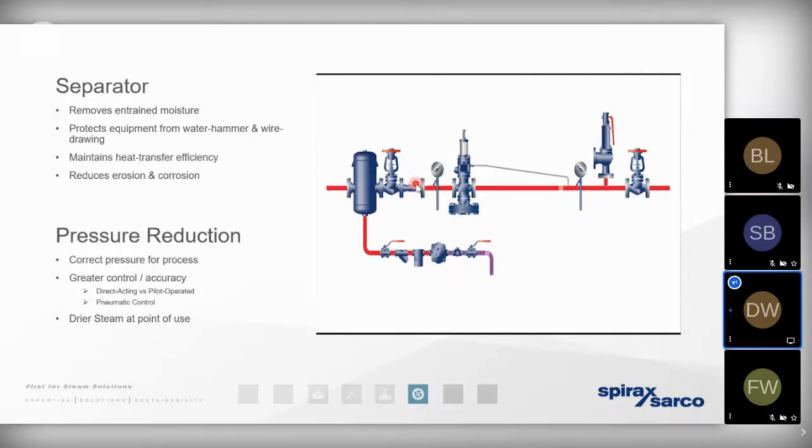Steam conditioning is very, very often overlooked. It's taken out and never replaced, or it's value engineered. And it can have an enormous impact on ensuring that the process is working efficiently, ensuring that we don't get capital equipment damage to the various valves and flow meters, and ensuring that we're not contaminating the heat exchanger with an excess of rust or scale that can create a barrier to heat transfer. So please just check, just have a look if you've got any capital equipment that has got these conditioning ancillaries missed. It can have a hugely positive effect.